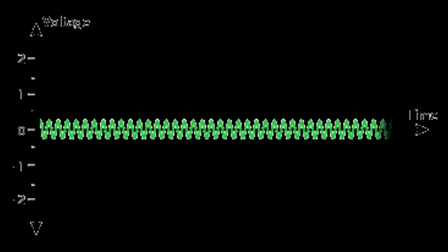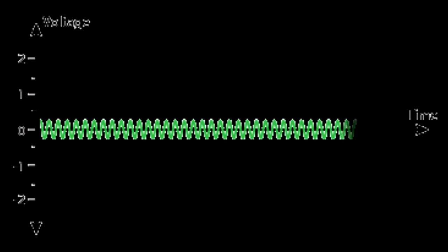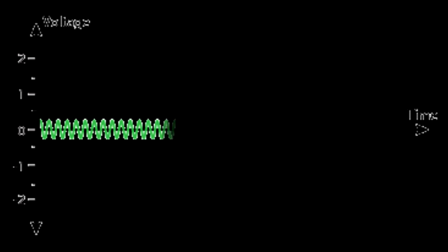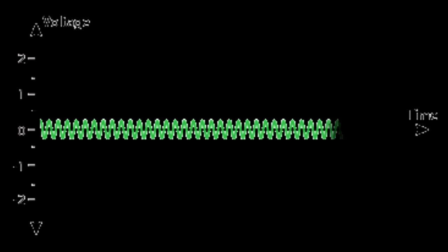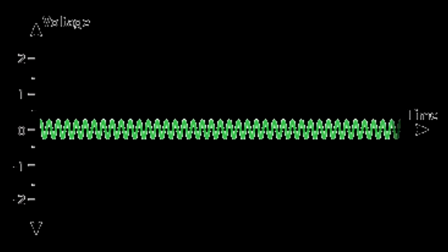The difference between an analog and a digital filter is that digital filters need to be converted with an analog to digital converter to change into binary numbers, which will then be processed with a microprocessor and converted back to an analog signal using a digital to analog converter. Analog filters, however, will use an analog signal the entire time it is being filtered. The good things with digital filters are that they can filter very low frequencies, are easily standardized, and most things already come with a microprocessor.